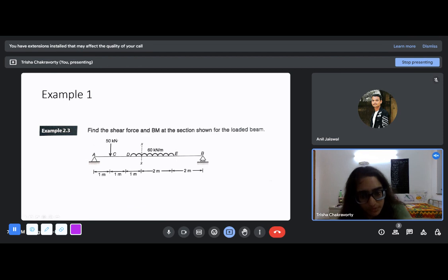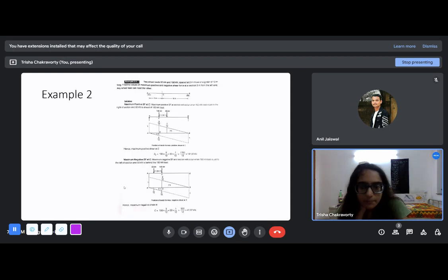However, if you use shear force and bending moment concepts from equilibrium, the moment I apply this force, the reactions will change. So you have to treat the problem as a new problem as the loading changes. But in ILD, the problem doesn't change as the load changes, because the ILD remains constant. You just have to put the loads and calculate the corresponding ordinates or areas.